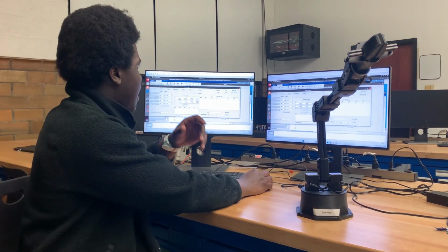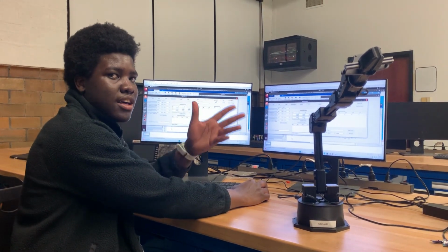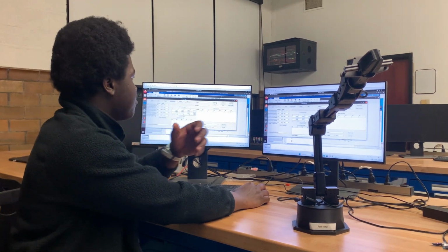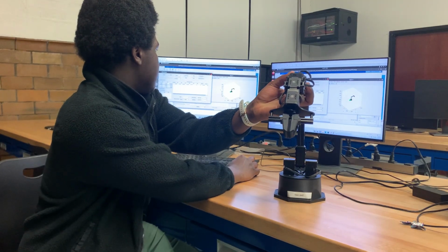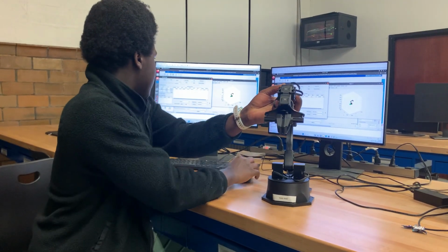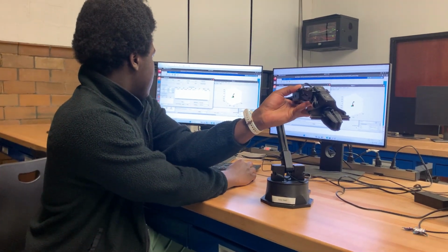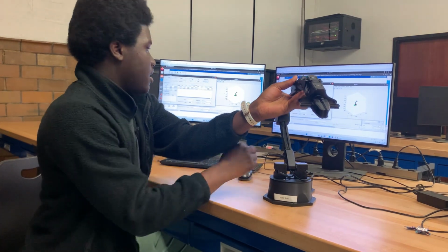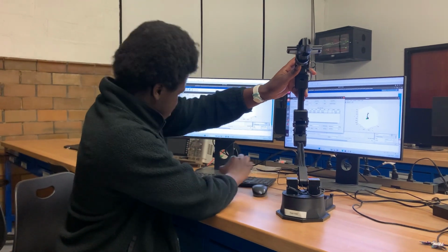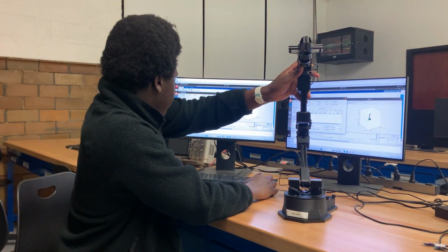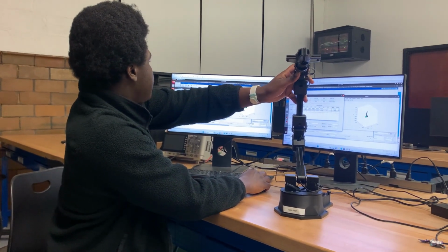And some other functionalities, you can actually store different positions and teach the robot how to play a sequence of movements. So for example, if I relax the robot into a different position, set the move time to 2 and the acceleration to 0.5, store the point, and then I want to take it high and make it actually slower. I'm going to make it slightly faster than this, 5 and acceleration 1, and store the point.